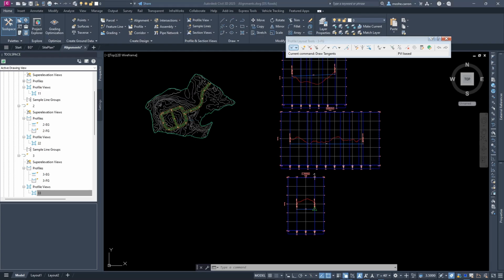If you were doing more roadway design as opposed to grading, you would likely try to match your ups and downs closer to the existing ground to avoid high volumes of fill and cut and have a better earthwork balance. Taking a look at our finished model, we now see that we have profiles for the existing ground and finished ground, seeing how nice having good naming conventions come into play. This one being an existing surface, this one being our design, and for each of the three to start.